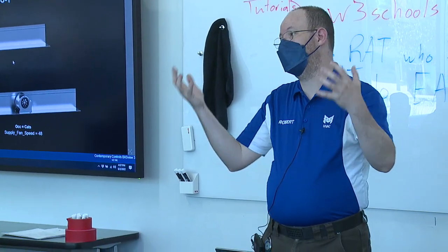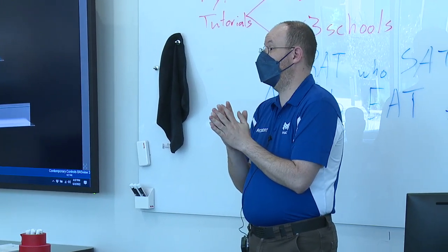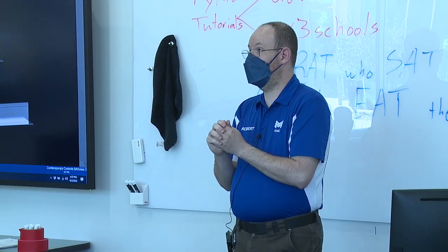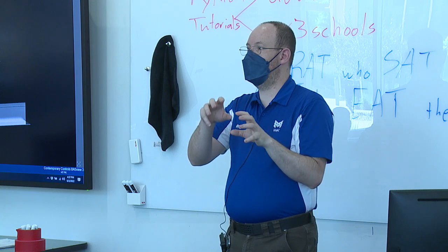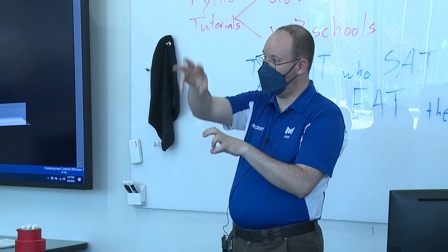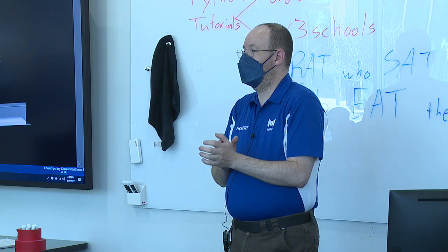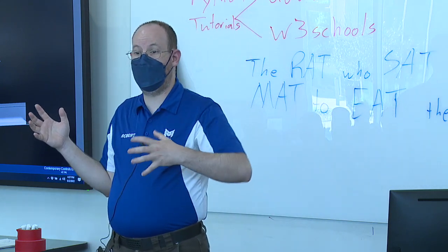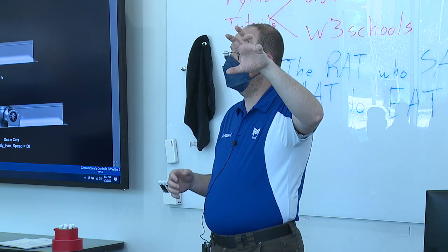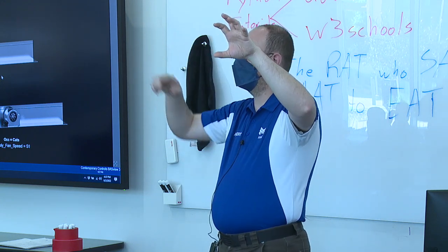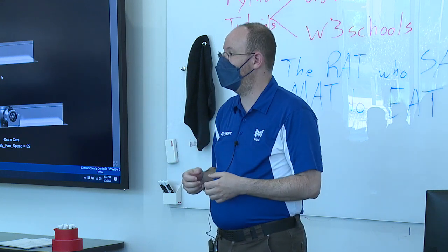Okay. One of my great favorites was copying a graphic in Andover controls. In Andover, you had to copy the graphic and then go break the link to the old background file, or whatever change you made to the new graphic applied to the old graphic. I did that on a floor plan that I snagged for a very small project, a whole 3 VAV boxes. So I went from an emergency room graphic that had about 30 VAV zones to an MRI room that they literally built onto the side of the building that seriously had 3 zones. And I wiped out the whole old graphic except for 3 of the labels, and I drew my MRI room, and I hit save, and I was just so happy.